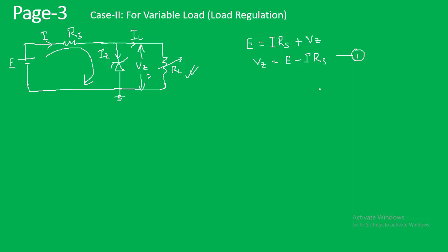Now if the voltage across the diode is less than Vz, the diode is evidently off and hence it acts as an open circuit. In our previous lecture, in the equivalent circuit that we have seen, when Vz is greater than the supply or reverse voltage, then the diode acts as an open circuit. Now in such a situation, we have the total circuit resistance equal to Rs plus RL.